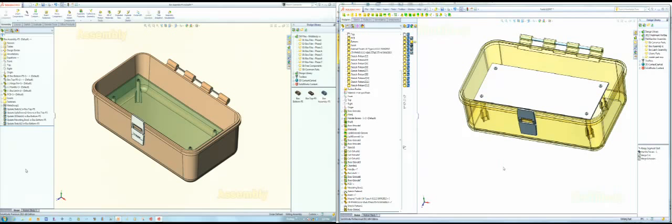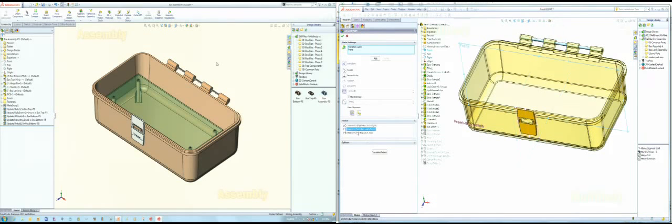You could, but the things below it in the tree would follow it. So in other words, your boss would follow it. What we can't do is make the boss independent and then position the boss. Well, I guess we could have. It's getting complicated, but yeah, we could move it. We can't edit those; you go in and edit the features. We could just go down here and edit this latch feature, and we could get back to those same mates and change them any way we want. So in a way we can move it, but you just have to remember the latch in this case is before the boss. So whatever you move, it's going to affect the children. I guess that's the way to think of it.